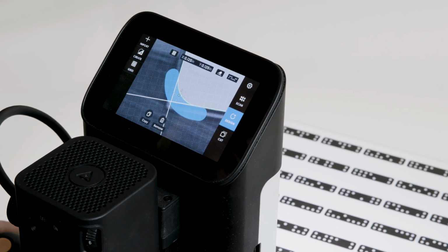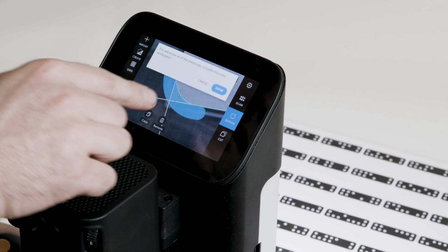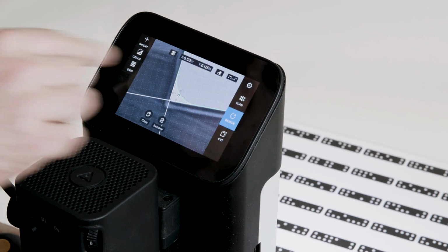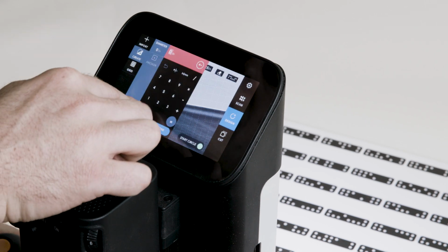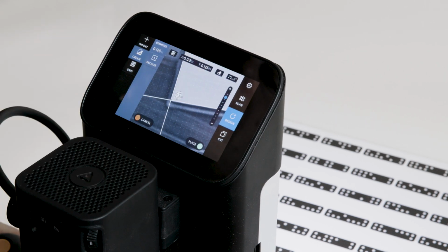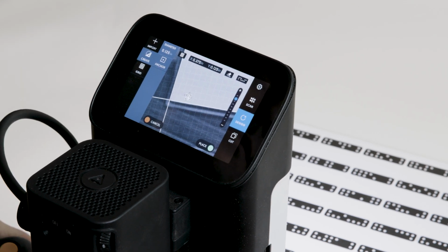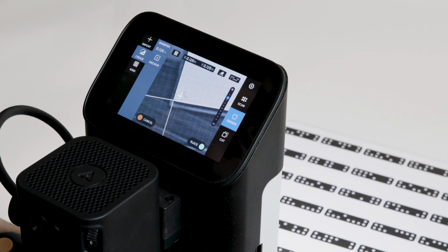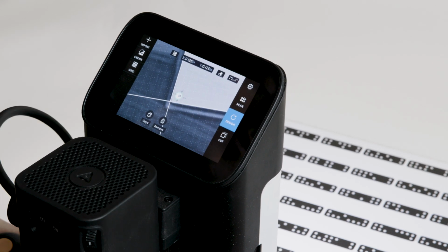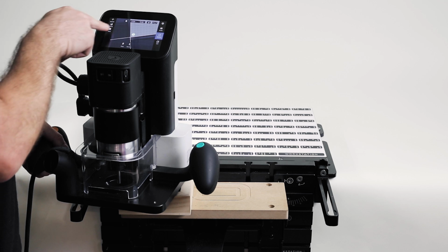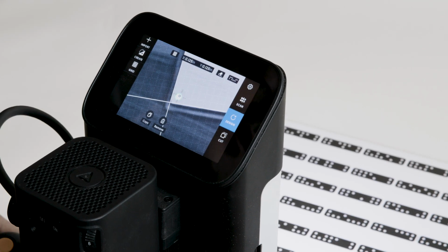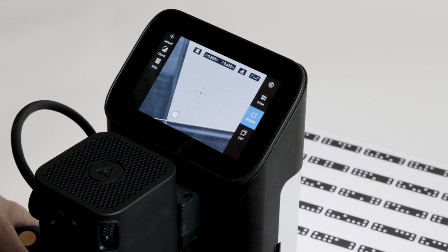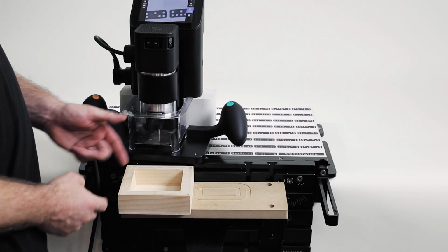So you'll see here, I'll erase my cuts and erase this old object, and I'll create a circle that's 0.125, and I'll place it at exactly 1/8 of an inch in from that corner. So you can see here how I'm jumping in 1/8 inch increments, and the anchor point is centered. You can see the value of modifying our grid increments and the fact that we don't need to re-grid whenever we do anything like that. So very powerful, very effective. So that's the standard gridding operation.